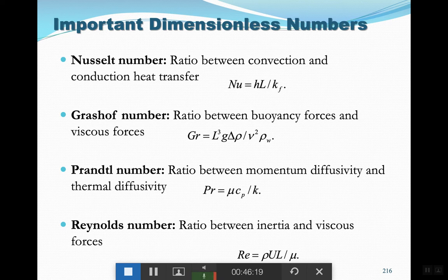And we will see in our turbulent example, once we get to that point, that being laminar or turbulent has a great effect on the amount and method of heat transfer in your system. As a general rule of thumb, any turbulent flow compared to any laminar flow, in similar scenarios and similar systems, has a couple of orders of magnitude more heat transfer.